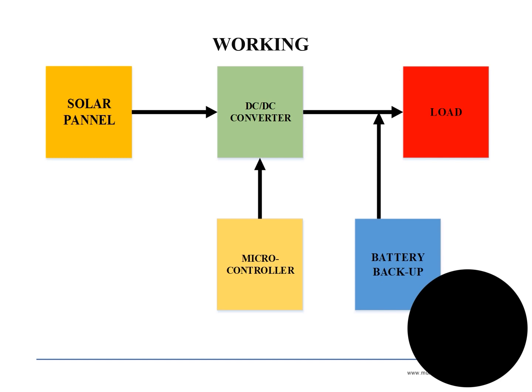The regulator is primarily responsible for preventing overcharging of the battery. My idea is to supply sufficient charge to the battery, so that it will get charged when there is light, and it will stop charging when there is sufficient charge on it.